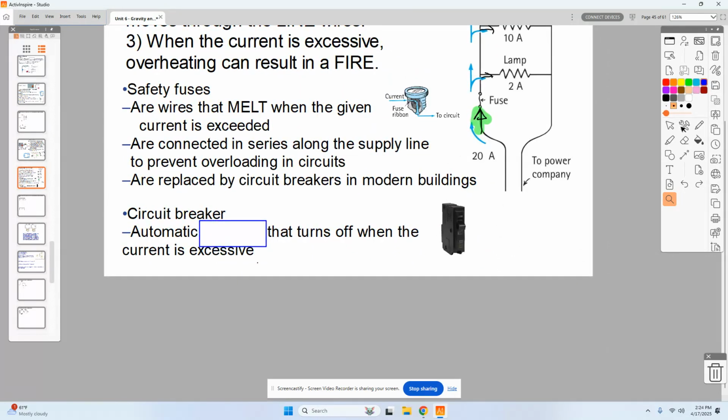Now, in most cases, things have been replaced with automatic switches. Automatic switches are circuit breakers. Essentially, many of these things work based on temperature, right? I'm just going to say it's like a bimetallic plate. These things are made up of 2 different metals, and when they have current flowing through them, they expand at different rates, and often what happens is when I have too much current, they'll just open up. And so the nice thing is that they can cool down, and then when they cool down, they'll close back. But a lot of them are done with what's called a bimetallic plate.